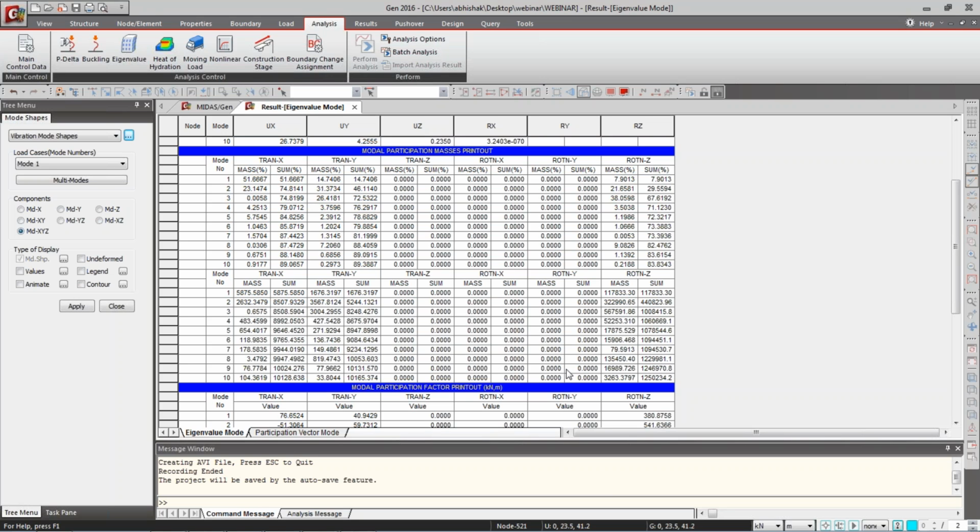Mr. Ruby Sunil, if you want to open a MIDAS Civil file in MIDAS Gen through the MGT command shell, you can do it, but it's not the entire model, only some of the commands or some of the features. It is not imported into MIDAS Gen because MIDAS Civil is basically for the bridge sector, and MIDAS Gen is for the industrial and building sector.